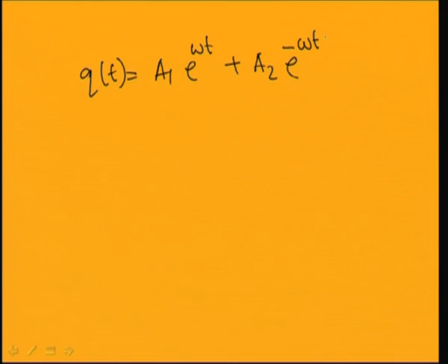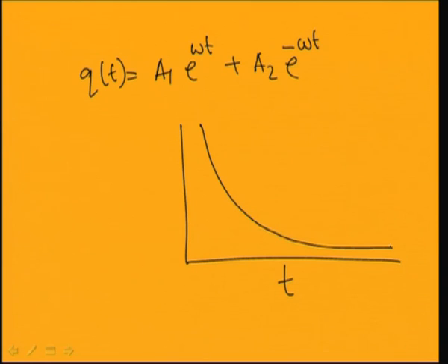So, in case of e to the power minus omega t, the response will die down and come to 0. For t equal to 0, this is a1. So, it will start at a1 and it will go on increasing as t tends to infinity. So, in this case the response goes on increasing as t tends to infinity, so the system will be unstable.